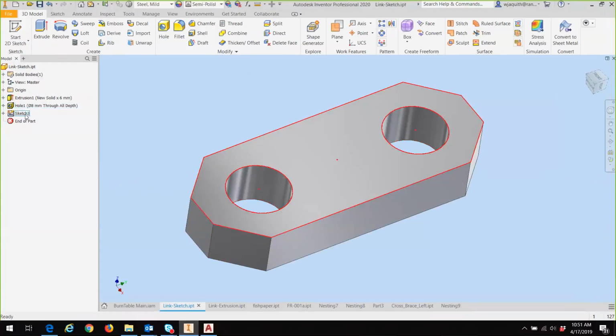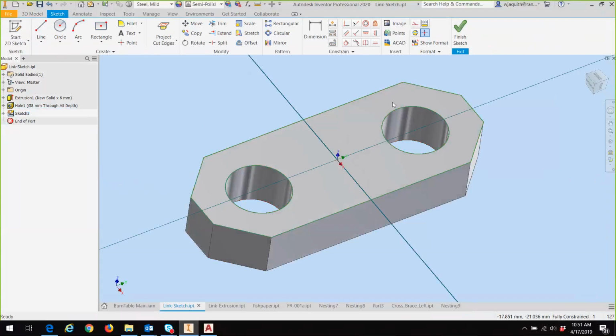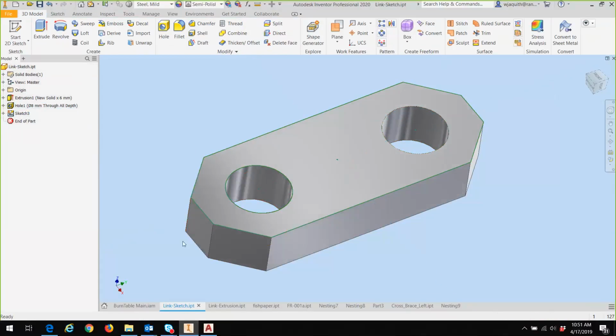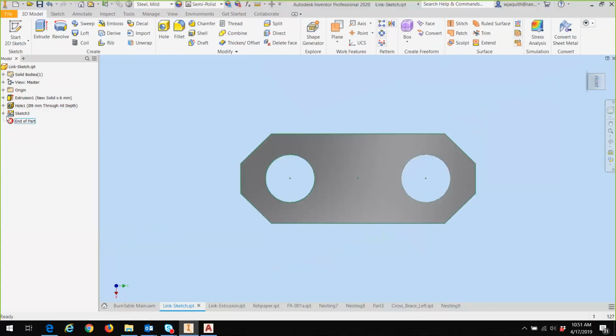Create a sketch that just has the features that you wanted in it. So, you know, if I edit this sketch and come in here and grab that circle there and make that one construction line. Okay, now if I nest this, I'm going to get this outer profile in this feature. So you would want to tweak it, create the sketch, make it visible, the last thing in the browser, and then add or project anything that you want. Okay. And that would be the way to do that.